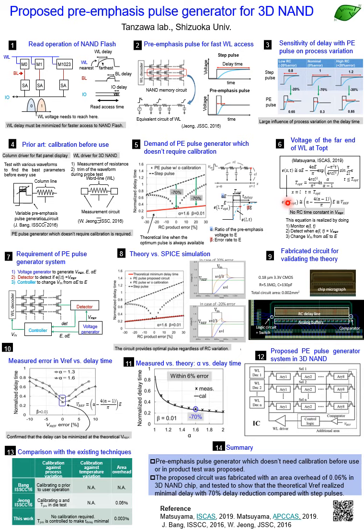So what you should do is the following three things. Monitor the farthest voltage node, and detect when that voltage reaches Vref. At that moment, you should change the input voltage from alpha E to E.